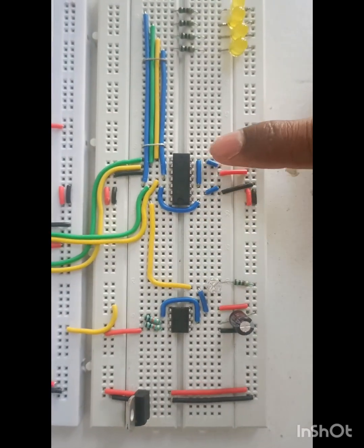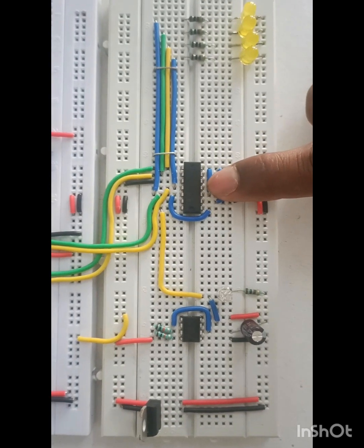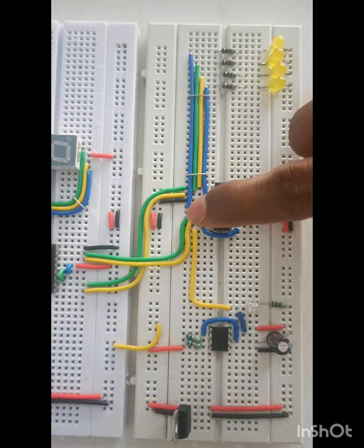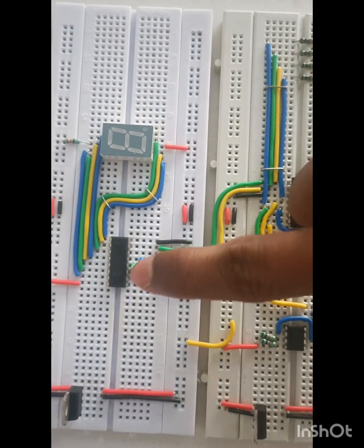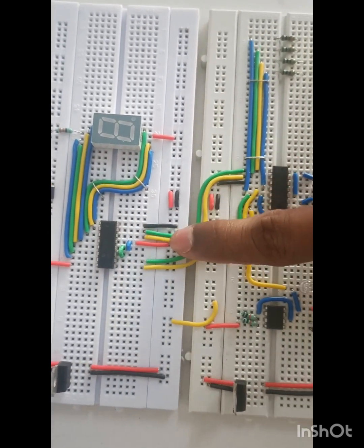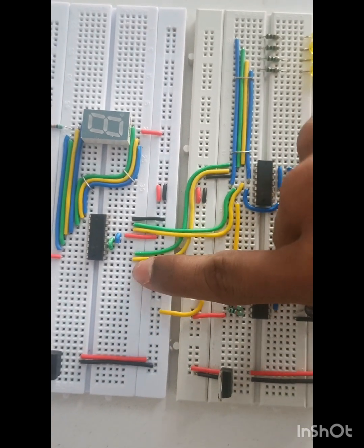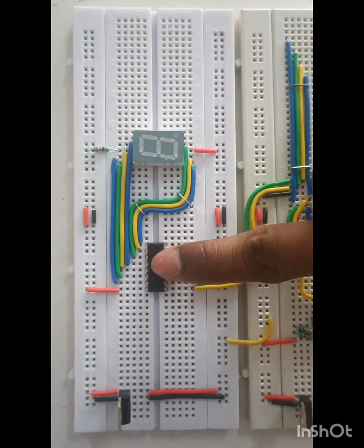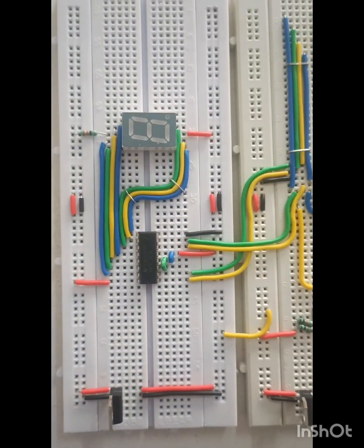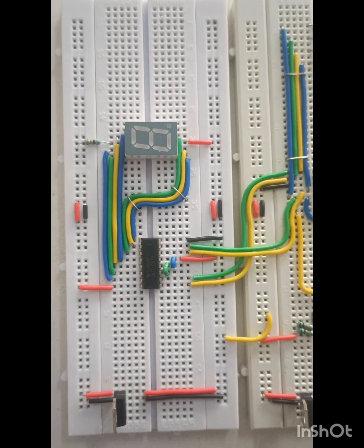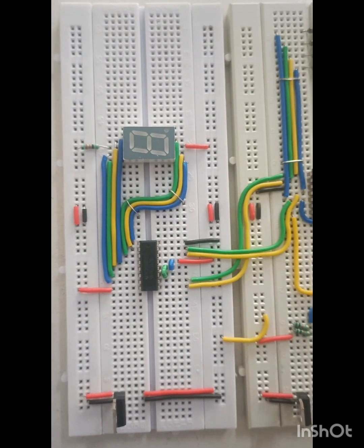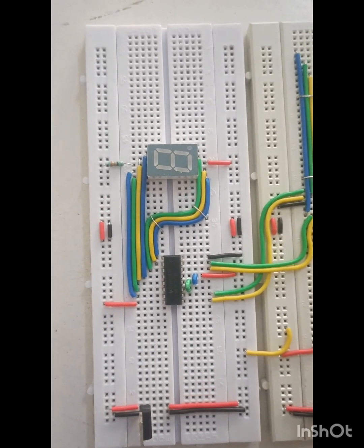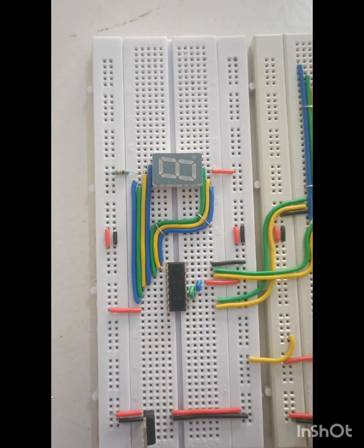It is a circuit of the decade counter using IC 7490, with output taken from pins number 8, 9, 11, 12 and given to the IC 7447 as the input at pins number 1, 2, 6, 7. This is the 7 segment display using IC 7447. The 7447 display decoder receives the BCD code and generates the necessary signal to activate the appropriate LED segments responsible for displaying the number of pulses applied.